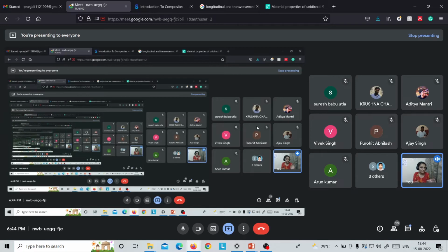So that is the glass transition temperature in which all the bonds which are easiest to break, mainly the hydrogen bonds and all the temporary bonds, ionic bonds and something similar, will all break down. That is the glass transition temperature. While melting temperature is that in which all the polymeric chains are separated from each other and start to flow. That is, the state of the polymer changes from rubbery state to entire liquid state. That is, it attains fluidity. So it starts behaving like a liquid.